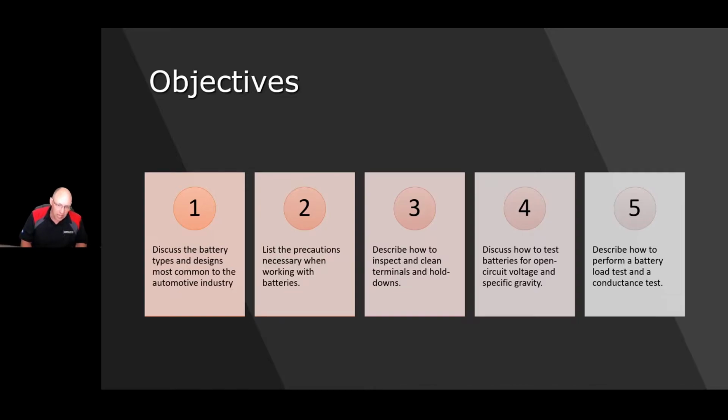Describe how to perform a battery load test and the conductance test. The other component to that load test comes down to a conductance test. We'll talk a little bit about what a conductance test is, how it works. It works under micro loads, not under a heavy saturation load. Okay. All right.